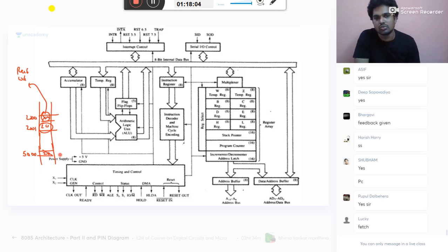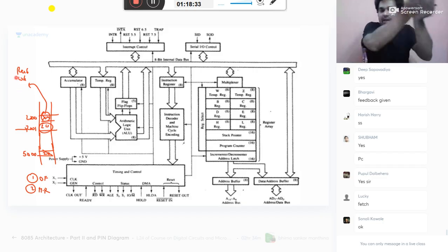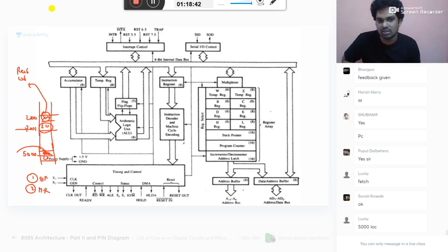Listen like a story. Okay, so the computer's first job is to read this first. Read is given the name of code fetch. Even though it is a fetch, it will decode, it will execute, it will understand the program. After reading this, it will understand I need to go to the next location. I need to read this data also. For that, we keep one name called memory read. It is reading this number from the memory and taking that and keeping it where? New location 5000. Why is it keeping at 5000?